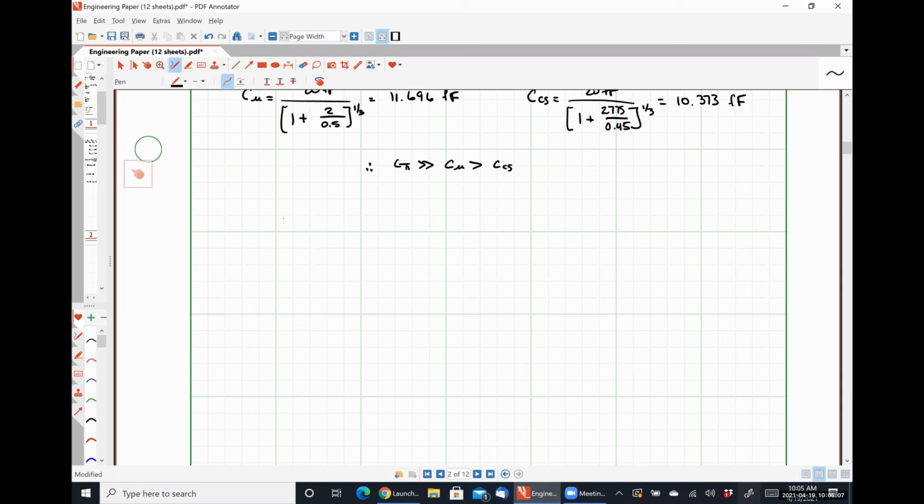So do any of you guys remember what beta fundamentally is? All right. So beta fundamentally is the short circuit common emitter current gain. So it is simply a relationship between the collector current and the base current, right? So we know, let me just draw a line through this thing real quick.